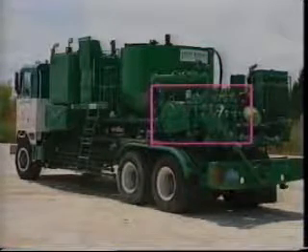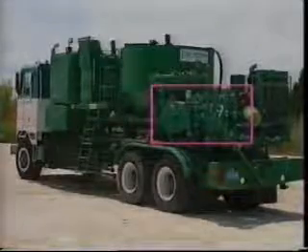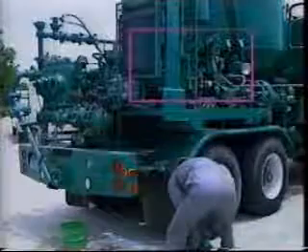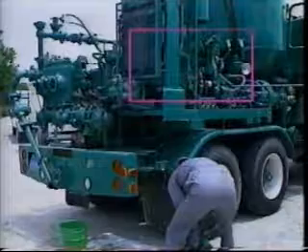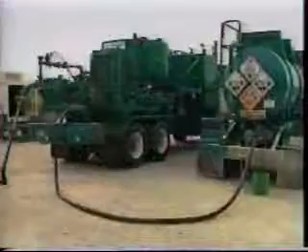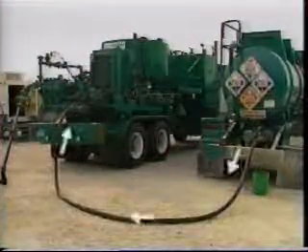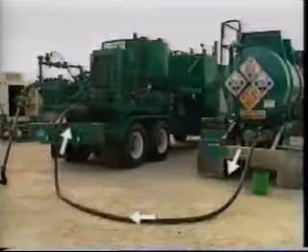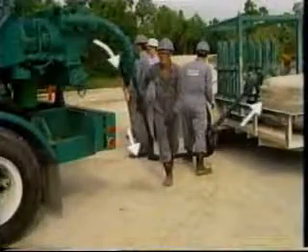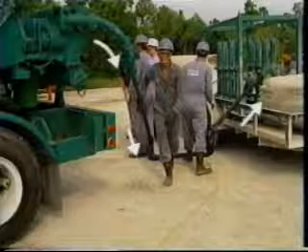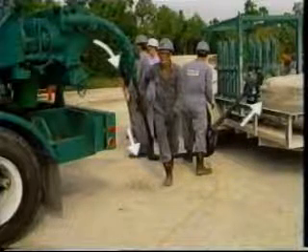Triplex pumps are also mounted on the rear of the pump truck. Powered by a diesel engine rated at approximately 300 horsepower, these pumps are capable of displacing from 8 barrels per minute at 0 psi to 1/2 barrel per minute at 10,000 psi. The triplex pumps draw acid out of the low-pressure line from the transport and discharge acid into a high-pressure line that leads to the high-pressure filter unit.